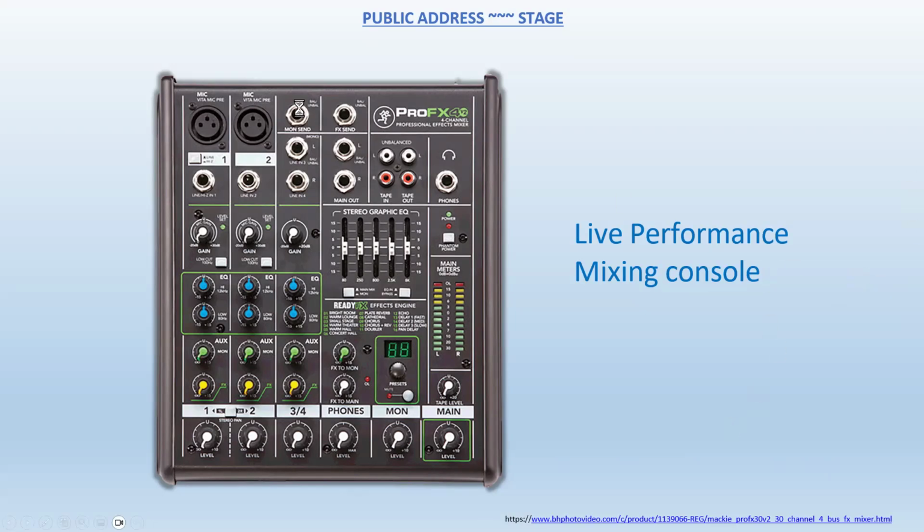So here's a channel strip. This gain control will make that signal usable. There's a line or mic setting. So line level from a keyboard is a strong signal, and microphone level is a weak signal. Line would be like 1 volt peak to peak, and mic like 1 millivolt peak to peak.